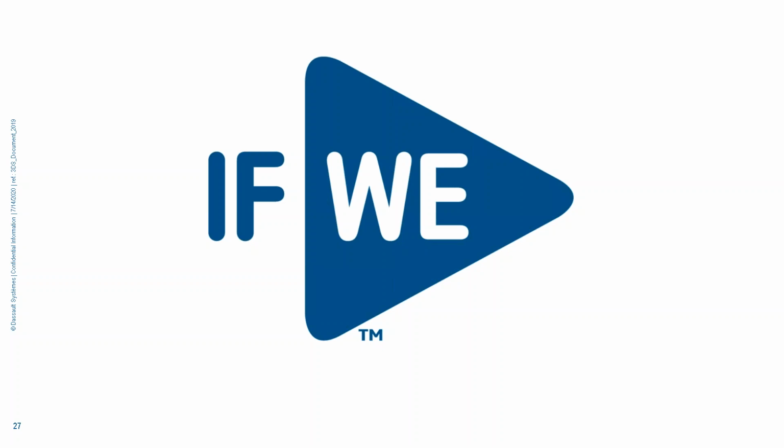So next question: how do schematics link to panel layouts, routing, and wire diagrams, and do terminal blocks get labeled? Yes, that's a great question, and I'm glad you brought that up, because there's a lot of things that were missing from this little example. But as far as a connection between a schematic symbol and its panel representation, we deal with a component. When I place that component in, within that I can have the manufacturer's part number assigned to it. The manufacturer's part number can define the schematic symbol representation and also the panel.